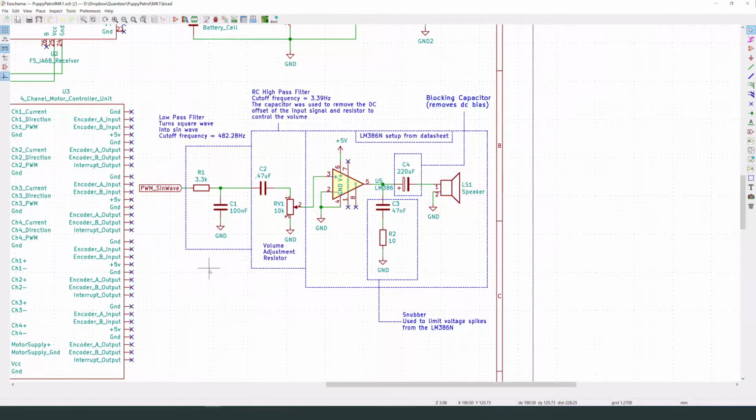And so what we're going to do is take the Arduino, which can only output a digital signal, and pulse width modulate that to ultimately create an analog signal that drives the speaker. And how we're going to do that is we're going to send that pulse width modulated signal into this low pass filter. And what that will do is smooth that out by charging up this capacitor and resisting that change in voltage, and it will create this kind of jaggedy sine wave at the frequency we're looking for. That will be at a DC offset, meaning it'll have a DC value.